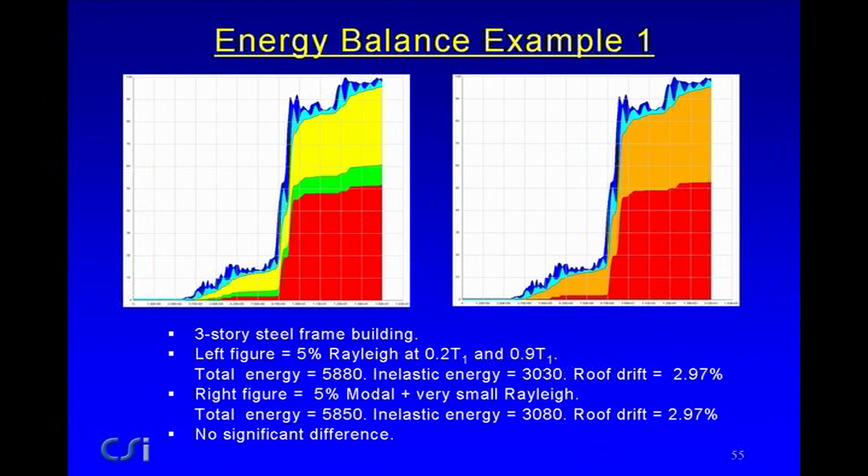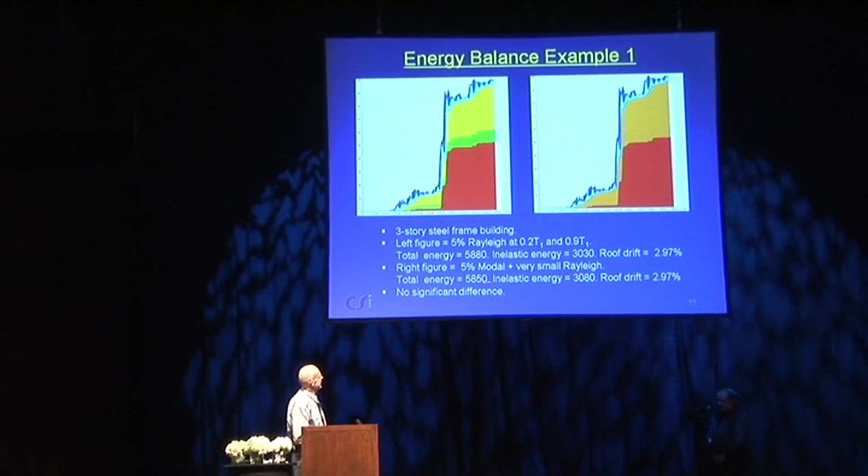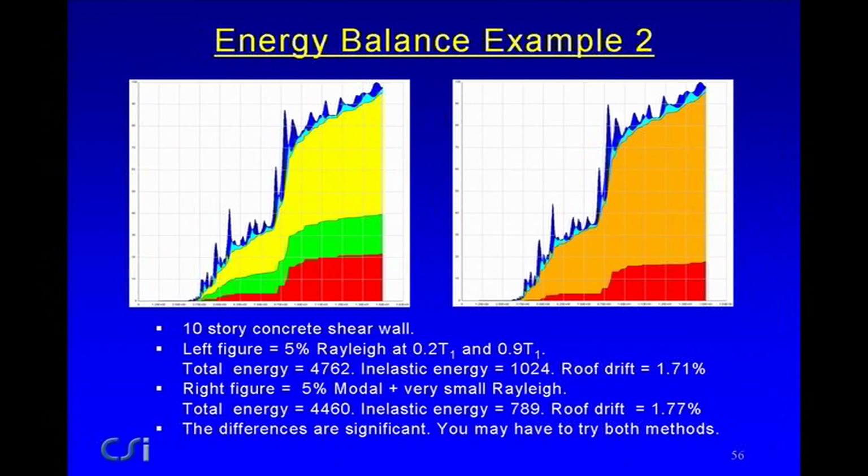When we do the same thing with 5% modal, very, very close total energy, very, very close inelastic energy, very, very close displacements. No significant difference for this frame for this particular case. It looks like both methods work particularly well. Of course, it's never quite as good as that.